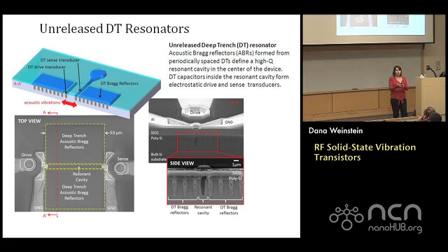So we have a capacitor formed inside the structure for solid dielectric drive. But we can also use those same trenches to form these acoustic reflectors, where we're leveraging the small acoustic impedance mismatch between bulk silicon and polysilicon in order to get the reflections.